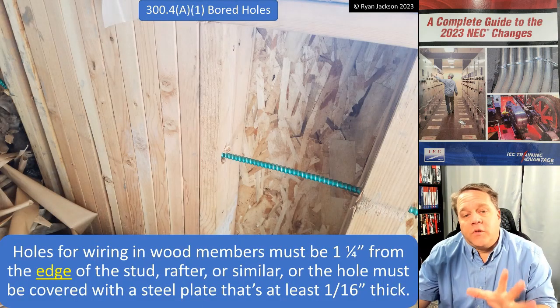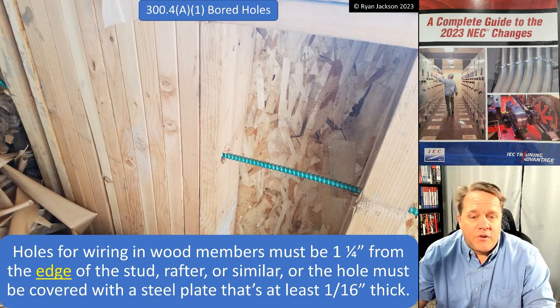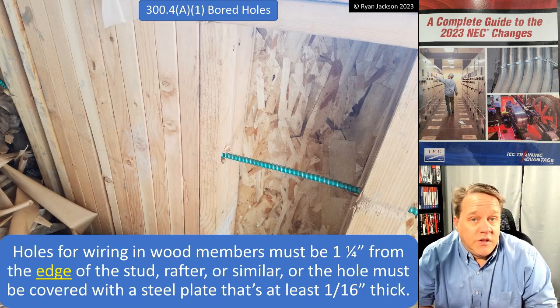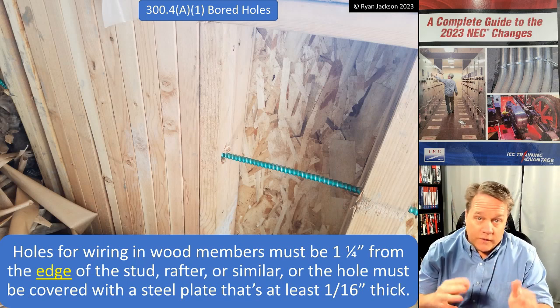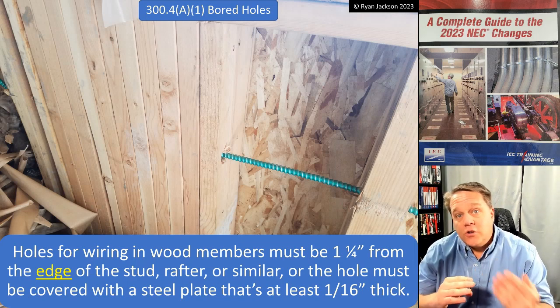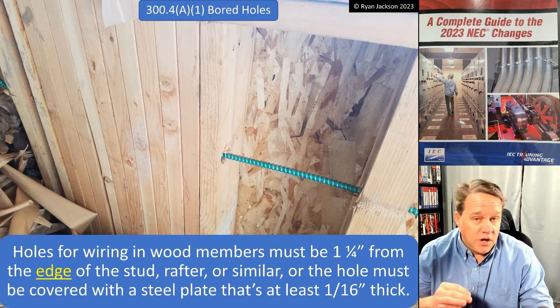Now, A talks specifically about bored holes through wood framing members. So holes for wiring in wood framing members must be at least 1.25 inches from the edge of the stud, rafter, or similar, or the hole has to be covered with a steel plate that's at least 1/16 inch thick. Now, this may not seem like a change, and at first glance, it probably isn't. The change here is it used to say that we needed to be at least 1.25 inches from the face of the stud. Now it says from the edge of the stud.